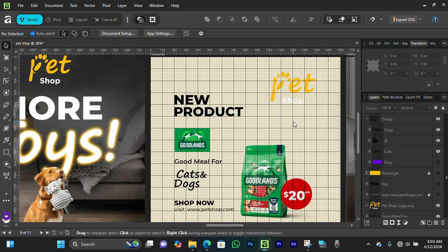I have activated the ruler option. We have the vertical and then we have the horizontal. I position my mouse pointer here and then I press and hold and then I drag it like this. So I start from where we have all the text and then I position the mouse pointer on this line and then I press and hold Ctrl. Instead of going here to drag again, I just use this shortcut. I press and hold Ctrl to make a duplicate and then I drag it like this to touch this side here.